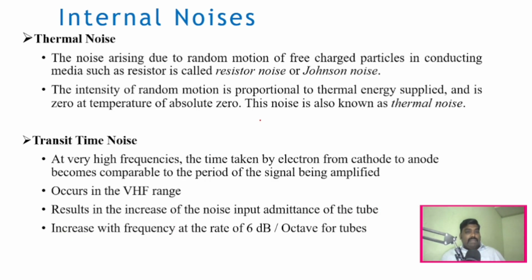Whereas coming to thermal noise, from the name itself you can understand, right? It happens due to the motion of charged particles, which is related to thermal energy, right? The noise arising due to the random motion of free charged particles is called resistor noise or Johnson noise. The intensity of random motion is proportional to thermal energy. As I said, the motion depends upon the thermal energy, right? And it is zero at the temperature of absolute zero. And this type of noise is called thermal noise.